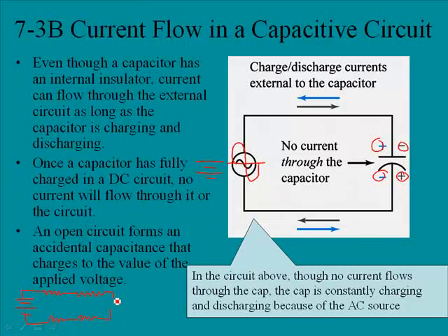And one of the things that we found was that when we had an open circuit, and I purposely didn't connect this, when we went in here with our voltmeter and connected across the 2 points of our open, we found that the supply voltage was felt right here.